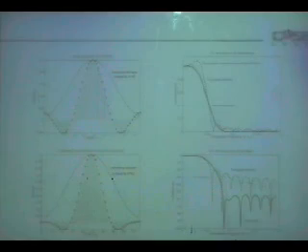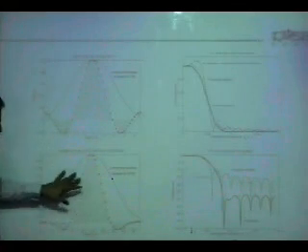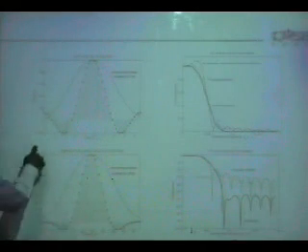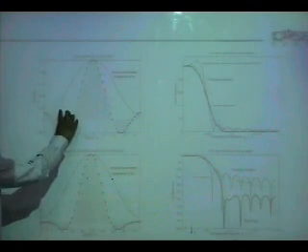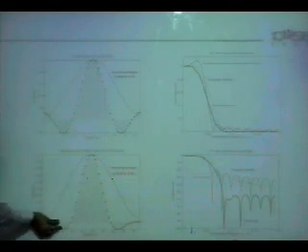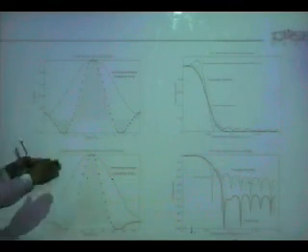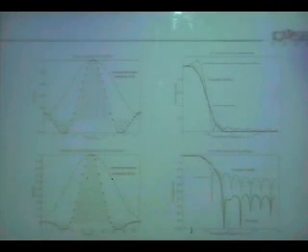So how you design, same thing. First you have a sinc. The sinc is multiplied by a window, so you get something like this. Once you multiply the sinc, as you can see here, this part will be multiplied by a smaller number, this part by a bigger number, so this part will be reduced. So you have a smooth truncation if you are using one of these windows.